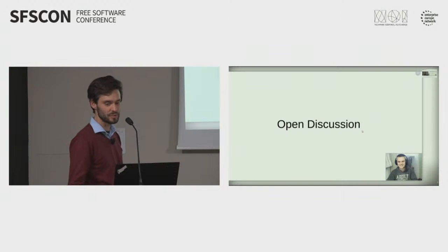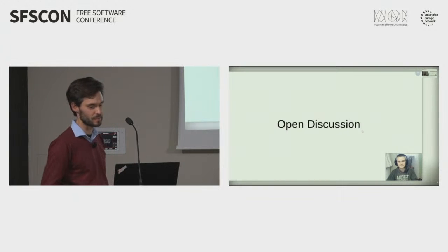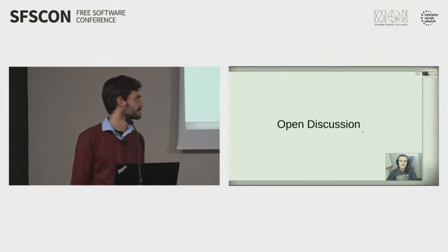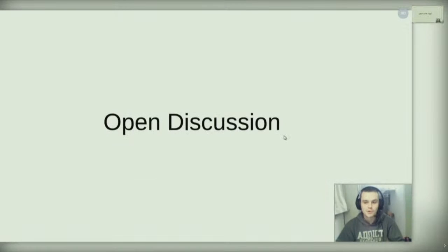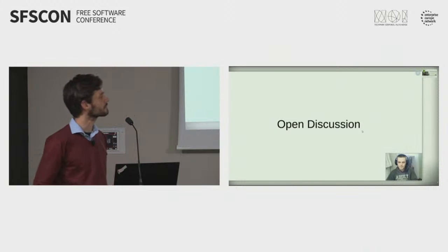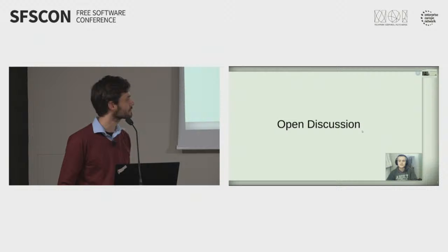Nice. Why do you use UDP and TCP between the Arduinos and the proxy? I used UDP just because I didn't find another easy way to broadcast my MAC address. So basically with UDP, I had the possibility to broadcast the MAC address over the network freely and set up a UDP listener on the proxy. And we use TCP to send the images.